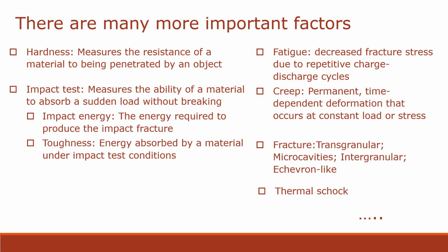Well, there are many more important factors when we are dealing with mechanical properties. And then hardness, I have told you about the differences when we talk about hardness in our everyday life and about hardness in the mechanical properties field. So hardness in this context measures the resistance of a material to being penetrated by an object.